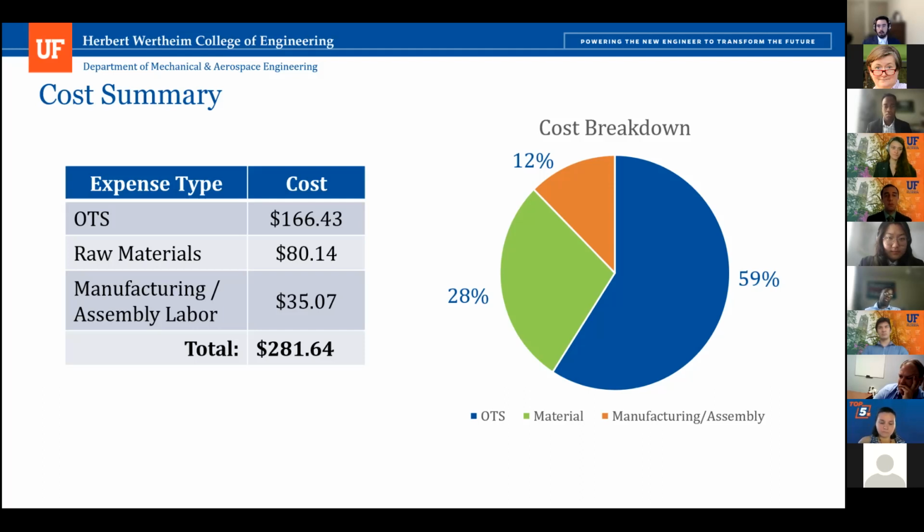It needs a frame to sit around, and under the wind loads present in Las Vegas, and under the weight of itself, especially because those plastics lose part of their material properties in that heat, any strain, any deflection, so if the square mirror were to bend at all due to wind loads or that loss in mechanical properties, now your light is being dispersed elsewhere rather than aimed at your intended target.